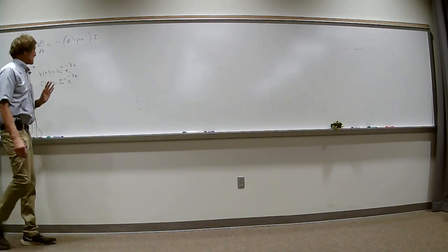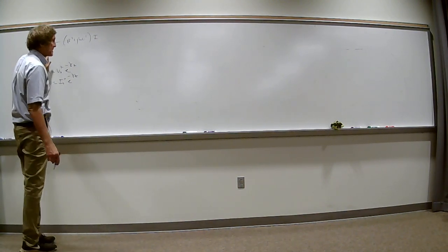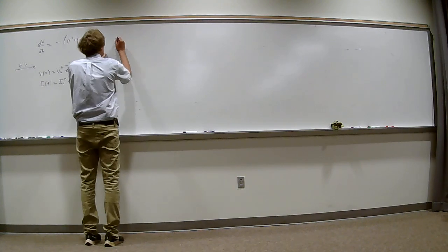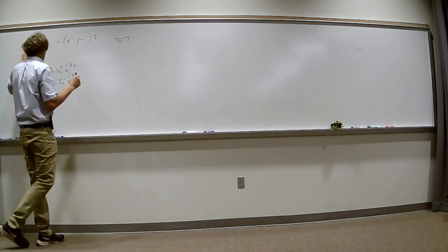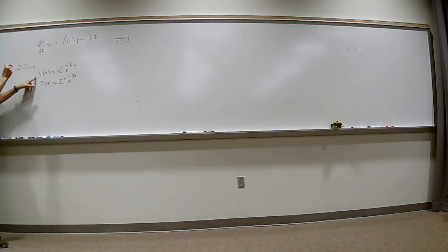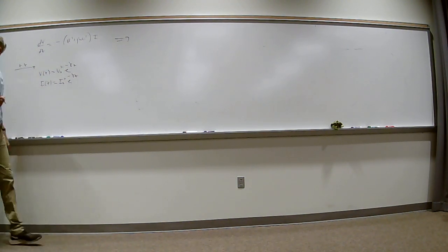Now, if I take a look at this equation, well, what is dV/dz? Well, that would be minus gamma V0+ e to the minus gamma z. Can everybody follow me on that? Just take a moment. Make sure you do. I'm going to take a derivative of V with respect to z. We just bring out the minus gamma.